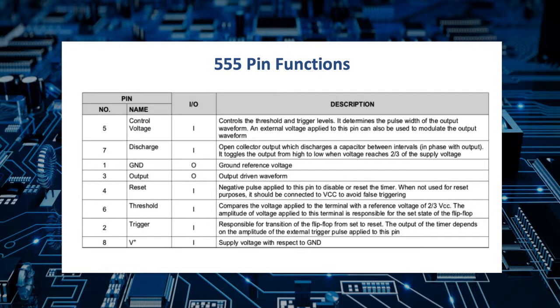Pin 1 is always ground, and pin 8 is always the supply voltage. Pins 2, 6, and 7 are used to control the timing for either the monostable or astable modes. Pin 4 can be used to reset the device, and pin 5 controls the threshold and trigger levels.